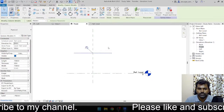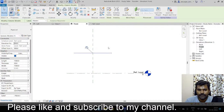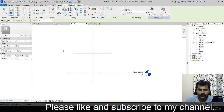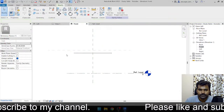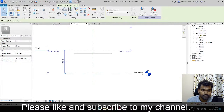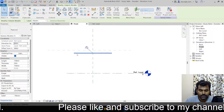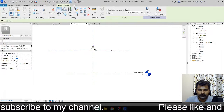In case you want to do it differently, you can draw a reference plane. Select this reference plane and keep it as top plane. Okay, so it's a top plane. Now just align this family to the top plane.